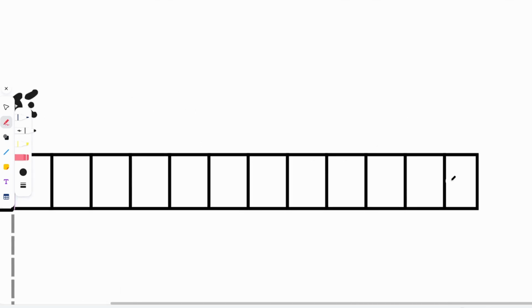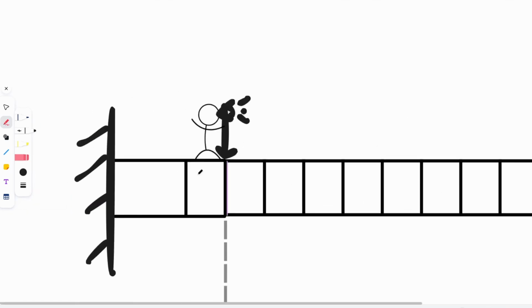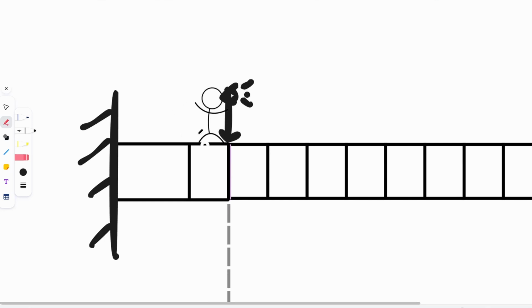So the reason why I drew so many elements is to make it absolutely clear that this shear force will only reflect in the graph once your point of observation has moved to the left of it.